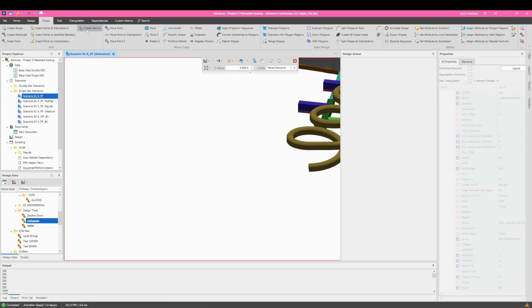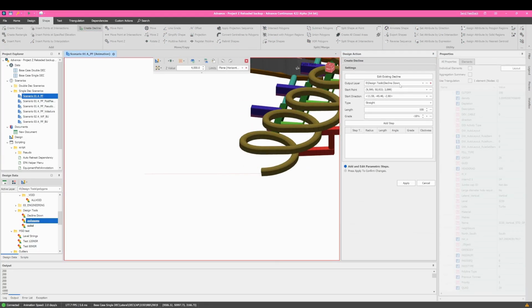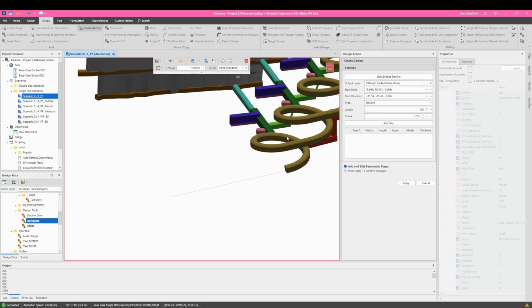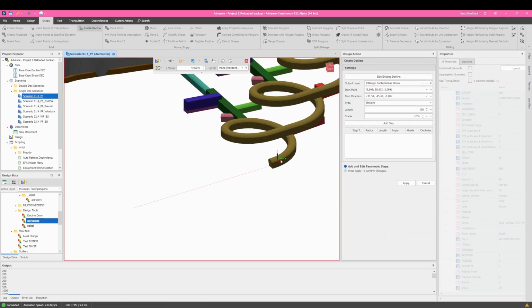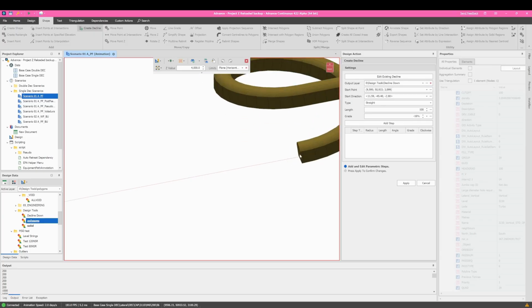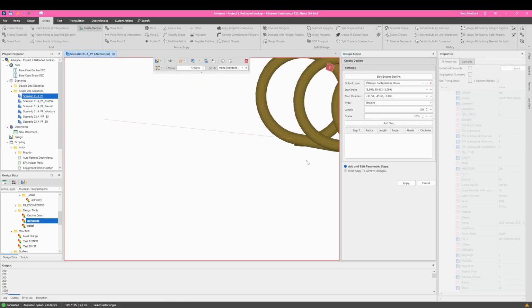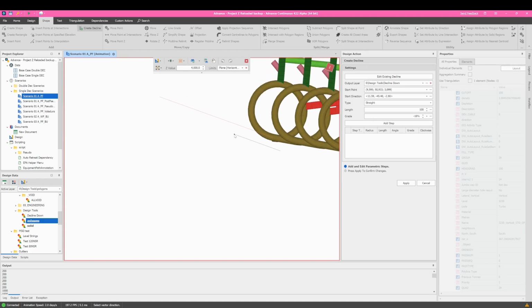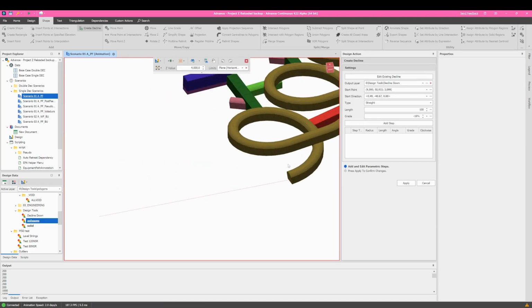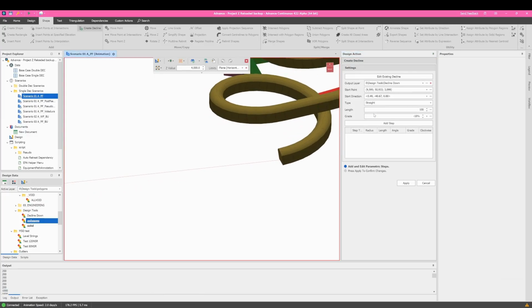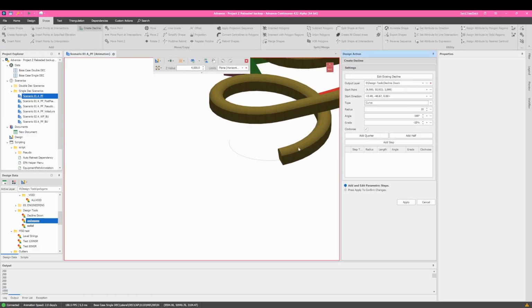So I'm going to open up the tool and first select an output layer. In this case, decline down. All we want to do is just a continuation, for example, of this decline. So we'll select the starting point that we just did and we'll select a direction of mining. In this case, if I want to go a little bit more towards the east, I'll just do that, and then I can select between a straight and a curved section. So in this case, let's go with a curve to start off.